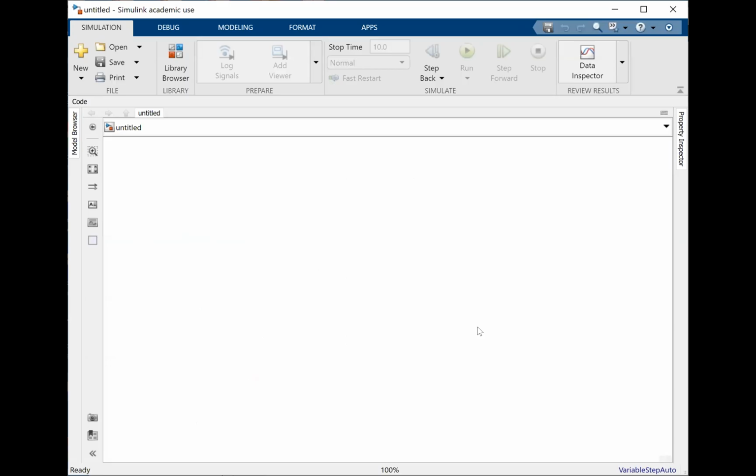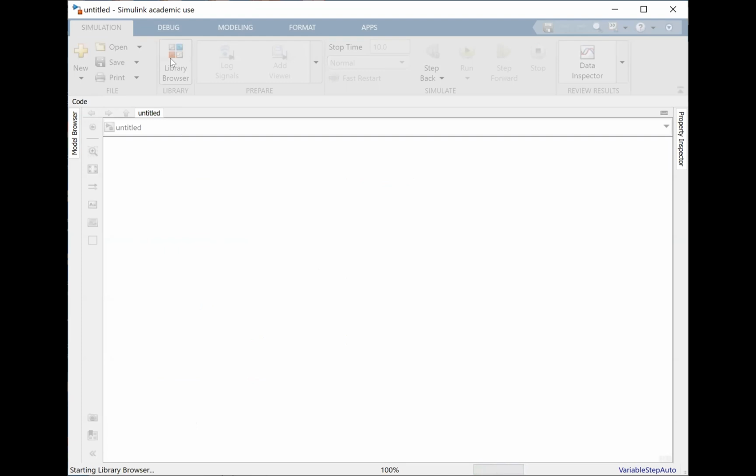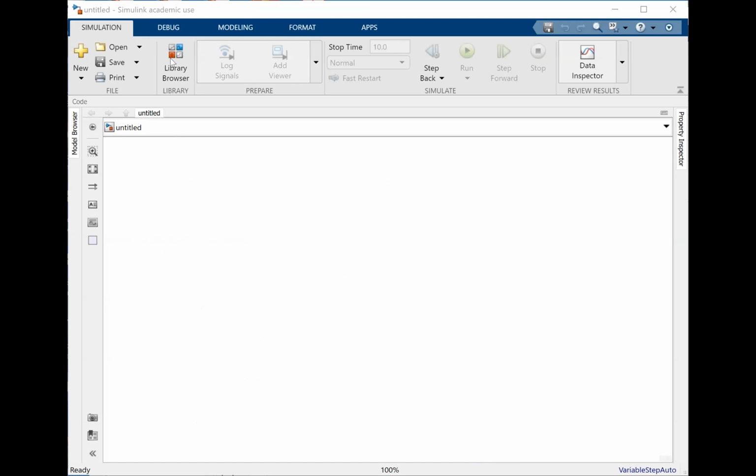So you should be able to open Simulink. And in Simulink, this canvas opens. And if you look at this canvas, I want you to go to the library browser. And in library browser, I want you to go to commonly used blocks. And let me see if there is continuous. And then you will see that there is, I'm looking for transfer function. Yeah, so can you see this transfer function block?